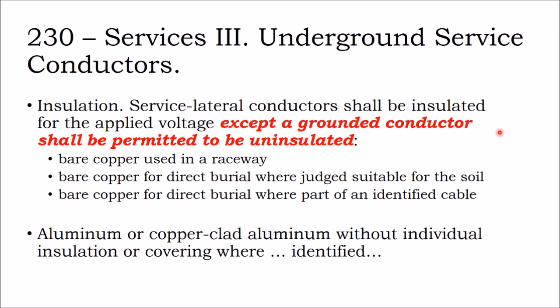So if I have a 600 volt appliance like a solar inverter input from the solar array side, I need to make sure that my cable is rated for 600 volts. Electrician cable is rated for 300 volts because they only deal with 120, 240. So 300 volt cable is fine. Although commercial cable on a 480 volt system, they might get some 600 volt cable. And then solar cable is often rated at 2000 volts.